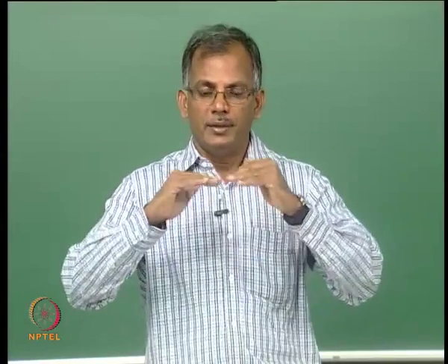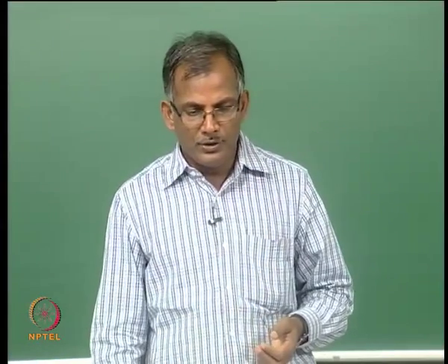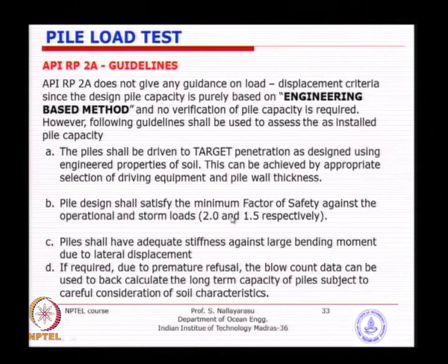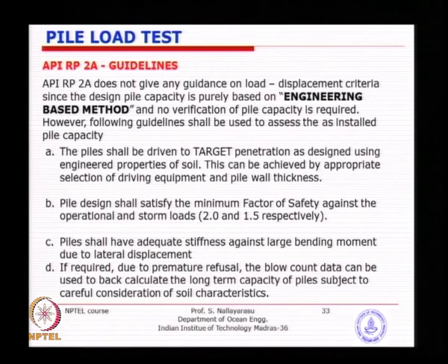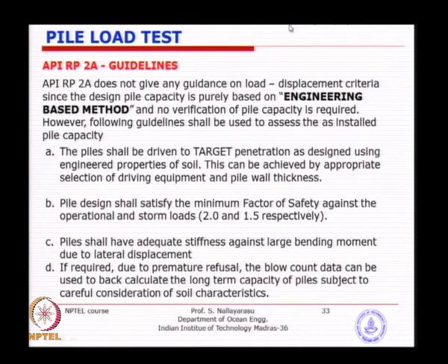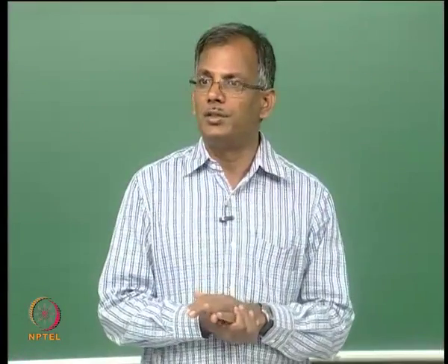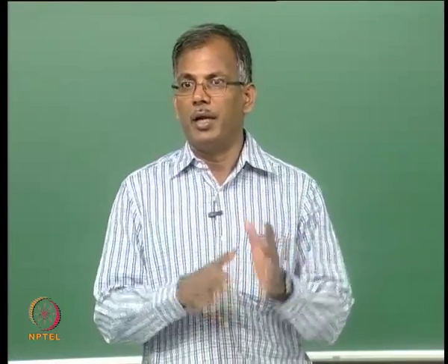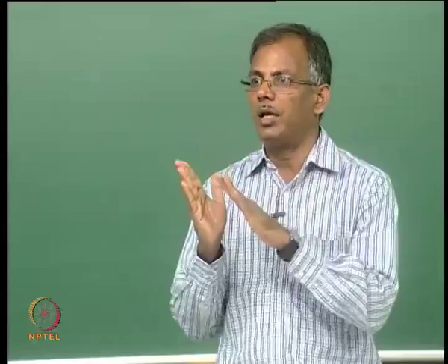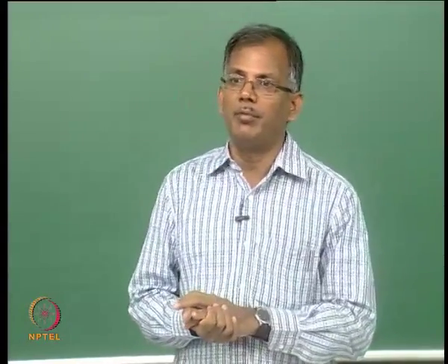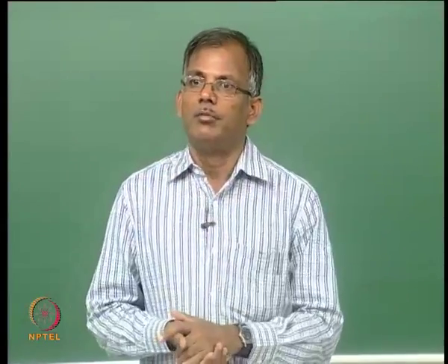So, that is why the method adopted by API is to design by the factor of safety, which gives you adequate safety against pile failure or premature failure, and at the same time you have a ductile material which is steel, and you are not worried about failure by other means of fracture, because the worry in concrete structure is larger displacement either in vertical direction or in horizontal direction, which can cause superstructure failure by fracture, because the concrete cannot fail in a ductile manner.